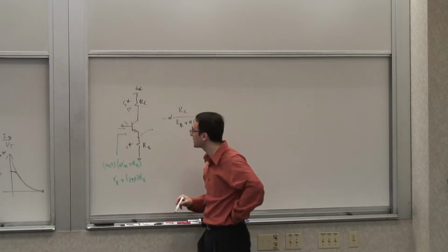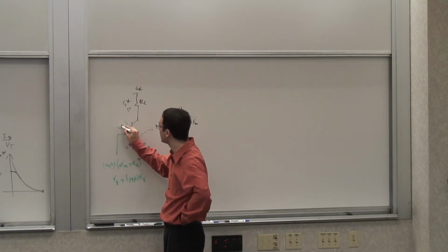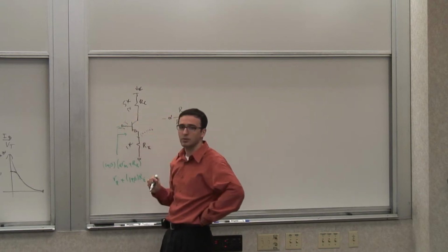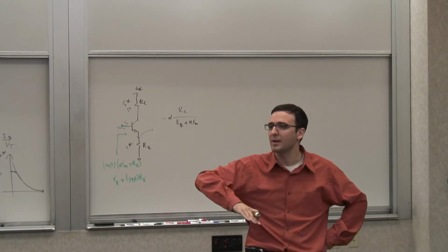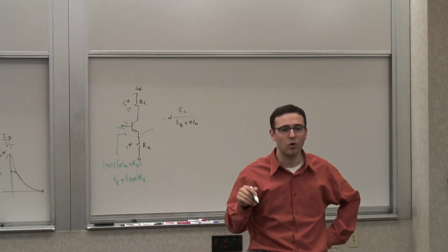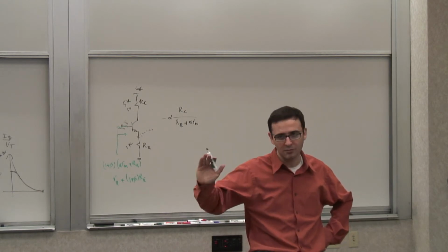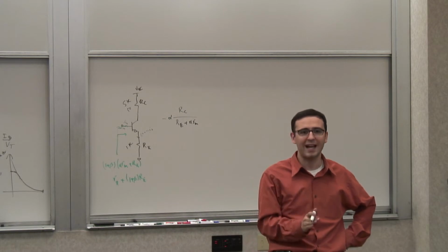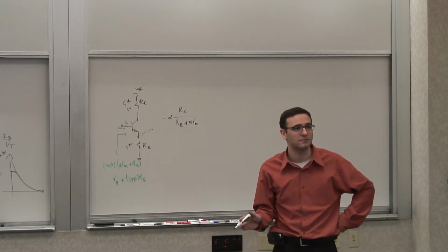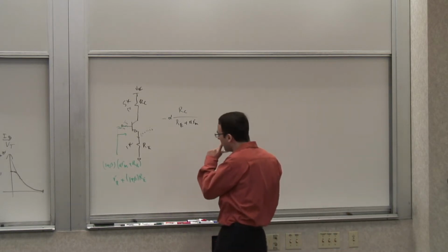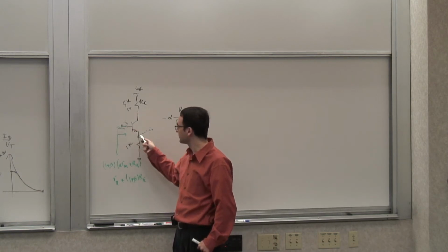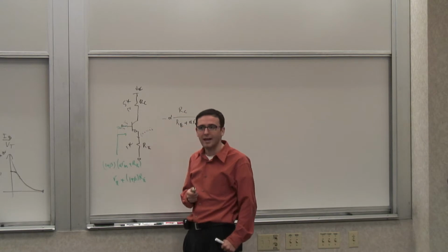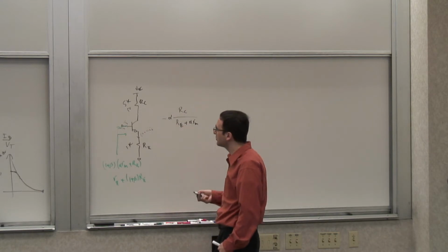You can also do the opposite. You can take an impedance from the base, if you have resistance here, and divide it by 1 plus beta, and move it to the emitter. Ballpark, multiplied by beta, divided by beta. For all practical purposes, the 1 doesn't matter. Beta is such an inaccurate parameter anyway. So for all practical purposes, multiply by beta here, divide by beta there. And that was a useful thing in determining the input and output resistance of this circuit.